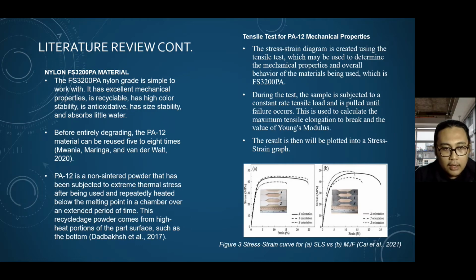2020. PA12 is a non-sintered powder that has been subjected to extreme thermal stress after being used and repeatedly heated below the melting point in the chamber over an extended period of time. This is recycled powder that comes from the high heat portion of the part surface, such as the bottom.